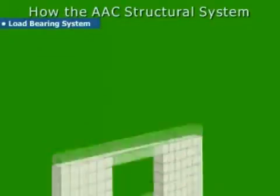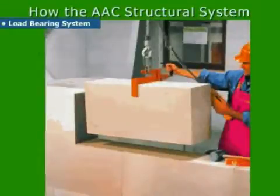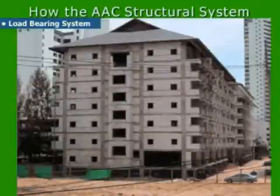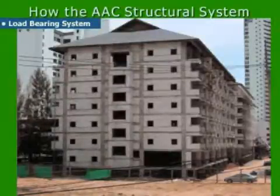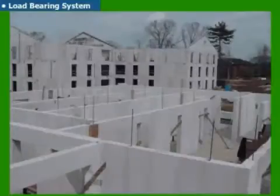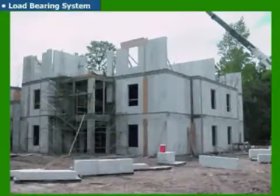So how does our structural system work? We can use standard blocks in sizes of 24 inches long and 8 inches high, and thicknesses in 2-inch increments: 2-inch, 4-inch, 6-inch, 8-inch, 10-inch and 12-inch thick. Or we can use jumbo blocks, which are 2 feet long and 2 feet high and have the same available thicknesses. Or we use load-bearing panels with a maximum height of 20 feet and a standard maximum width of 2 feet, which have the same available thicknesses as our blocks.